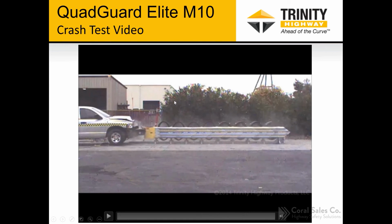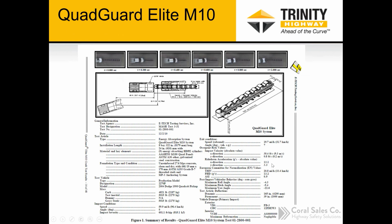So that same crash test that you just viewed, here's kind of a summary of it. One of the things I like to point out is the limit that MASH allows is 20 Gs of negative force on the occupants of the vehicle. With this system, we were at 13.1 Gs. So that's a very low number, lower than any type of system like this that I've seen. So that suggests it either has extra capacity or could possibly take a little higher speed impact and still meet the MASH criteria. But I think that's a pretty interesting thing to note in this system.